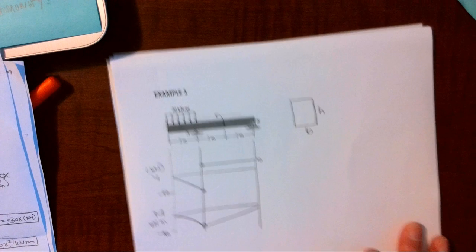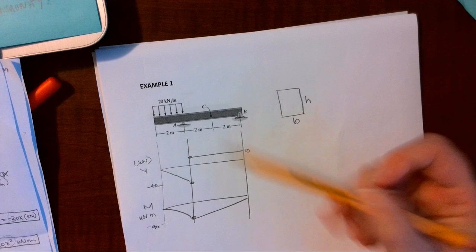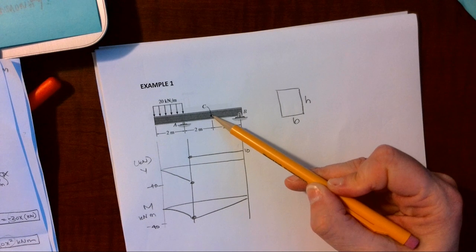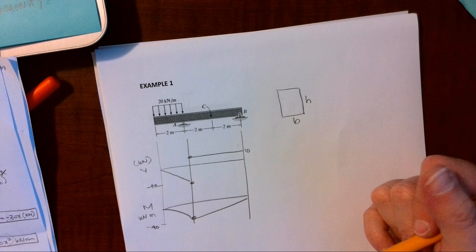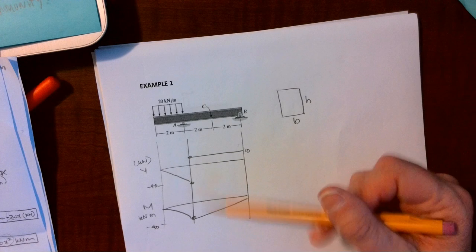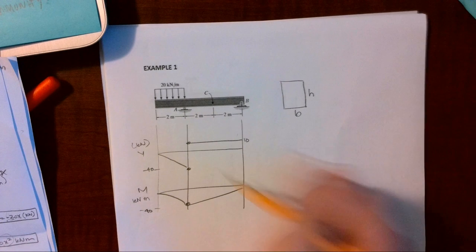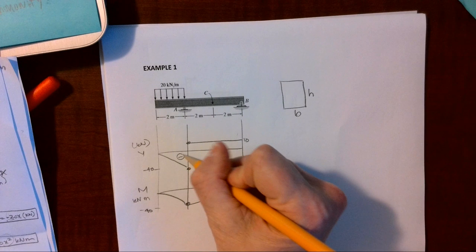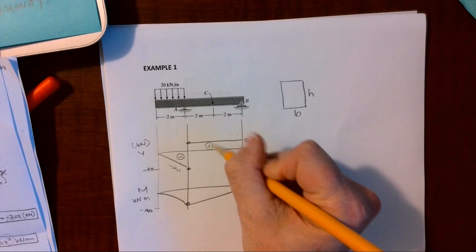We are going to continue using the same examples we did to find internal forces. Then we went through these examples and we wrote equations for shear and moment diagrams and drew them. And so now we have a working shear and moment diagram. We need to remember when we have negative shear, that means a negative slope on our moment line. When we have positive shear, that just means positive slope.